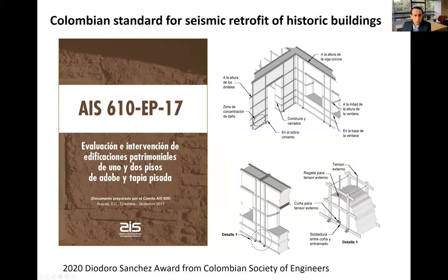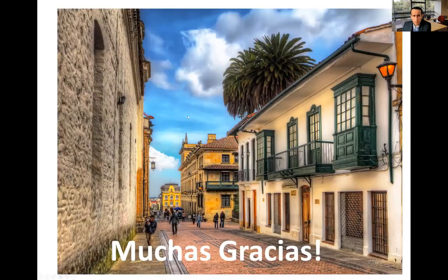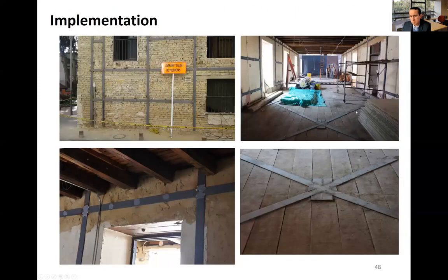And also these techniques are now implemented in some cases. Here, for example, they are also retrofitting the diaphragm, very important for connecting the walls between them and being able to take advantage of the redistribution of the forces when you have an earthquake.